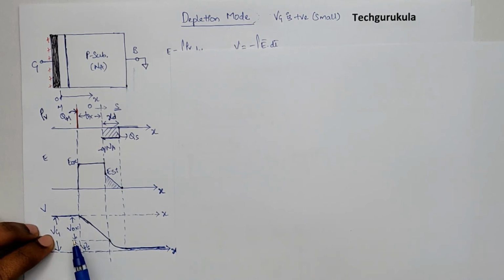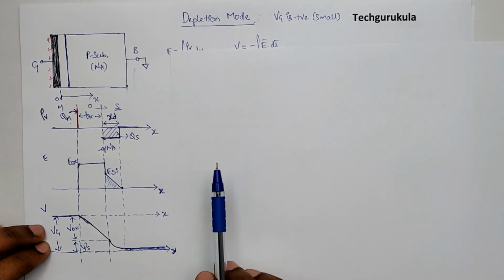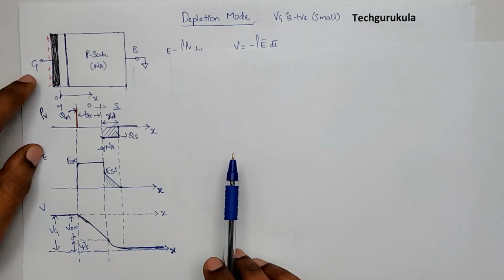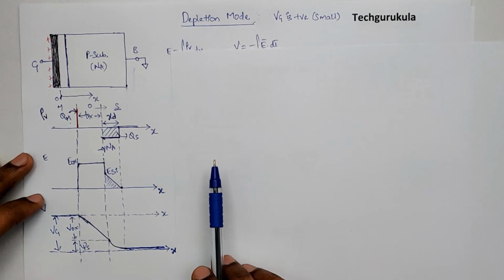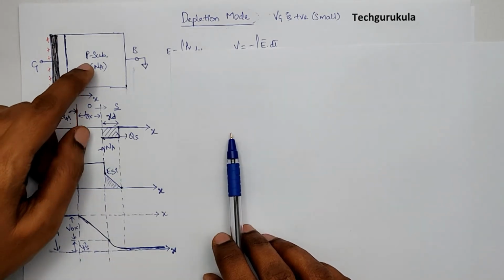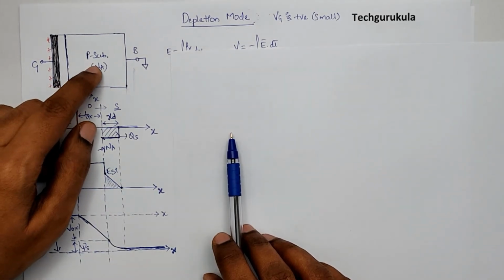Now, potential is defined with respect to positive charge, as we discussed already, but energy band diagrams are drawn for electron energy, which is negative. So if the gate is at higher potential, then the EF of the gate should be at a lower level than the P substrate, which is the semiconductor.